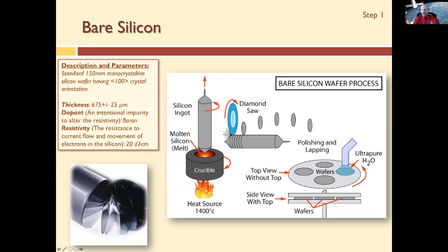So someone's got a chat question. How do they make the seed crystals? That's a great question. Well, if you make polycrystalline silicon, that's a grain. Then you'll have different grains in there. And typically what they'll do is use a small grain and create a larger crystal based on that. Then they'll determine the orientation of that, and then they'll break up that larger crystal into smaller pieces that are used as a seed crystal. Okay, good question. All right.